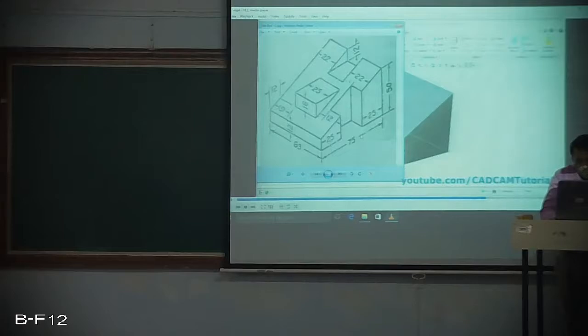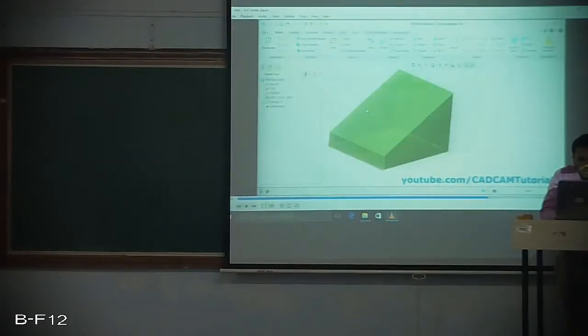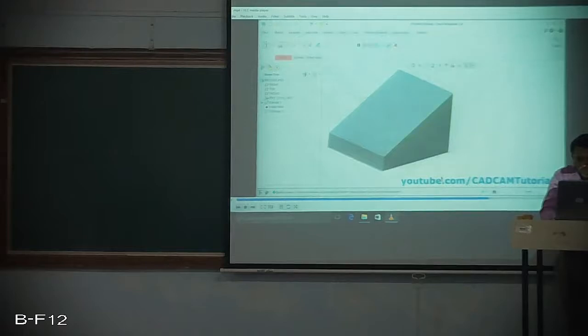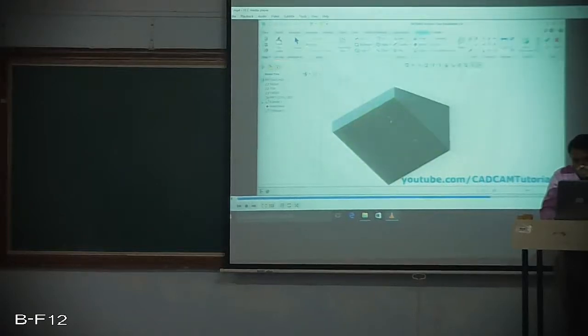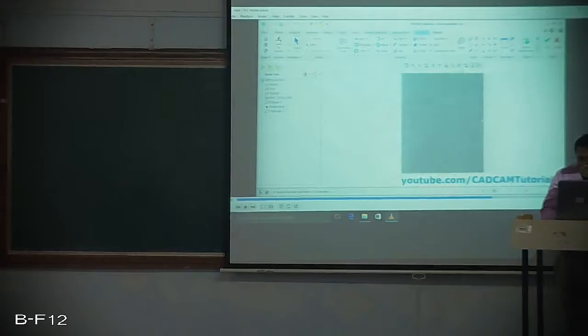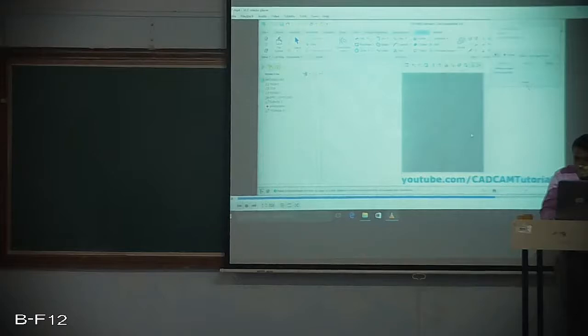Then I am going to cut this section by using the plane on the bottom surface of the block. The rectangle must be 25 mm away and 12 mm width. I'll choose that plane and then sketch, and the part will be oriented. Here I need to draw a rectangle, but for that I need to invoke the reference lines.